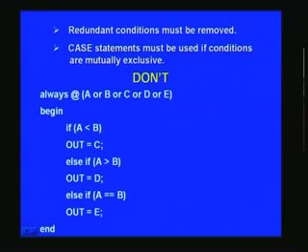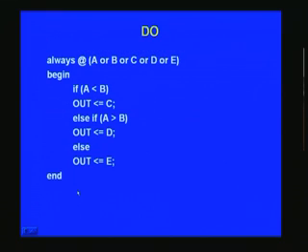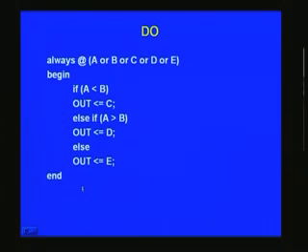So, now is there any other possibility? The solution is simple, and you can dispense with one of the muxes. After A equal to B, D is assigned, 2 muxes already present in service, and now we know that when we come to this step, it is already A equal to B. So, instead of putting else if, you just put else, and then E can be straight away assigned here. By doing so, notice that else if combined with else both means a single mux only, as we have seen earlier also, and that is how we save one mux and thereby improve the speed of operation.